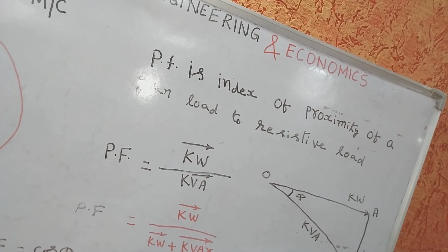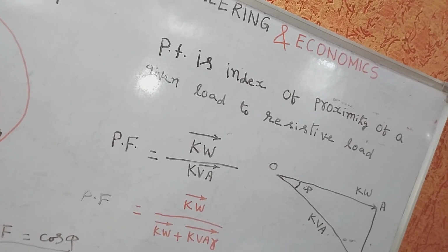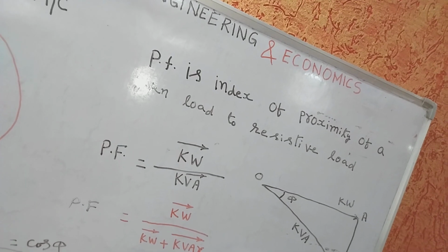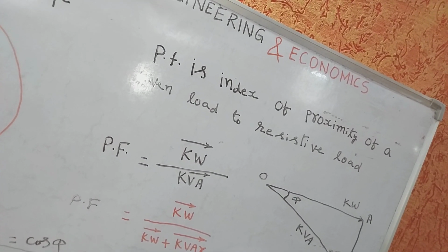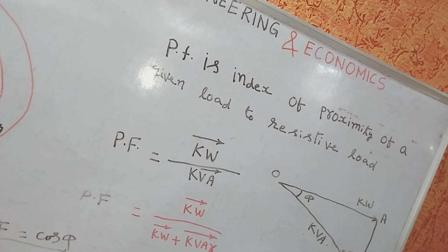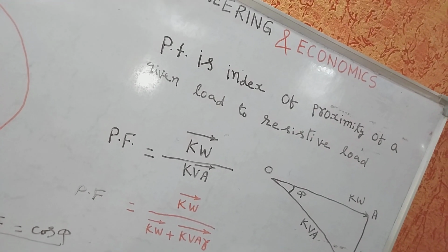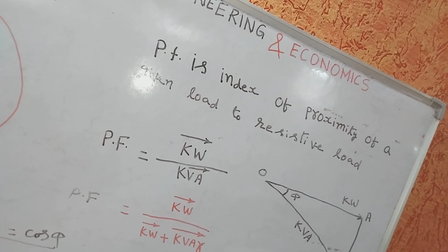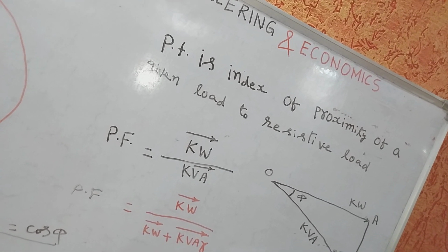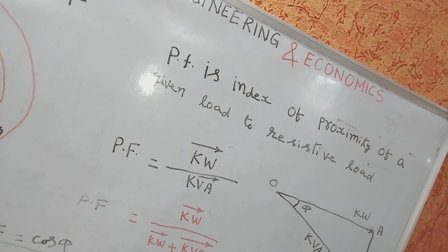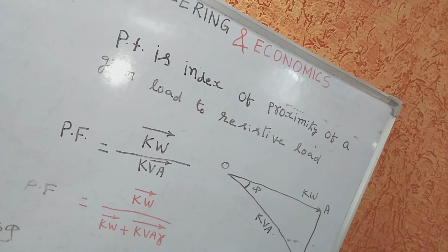In some cases, part of it is supplied from each winding, that is primary and secondary or stator and rotor both. If all or part of the magnetizing current is supplied to an AC winding, the input to that winding must include lagging reactive kVA because magnetizing current lags voltage by 90 degrees, as I discussed earlier.